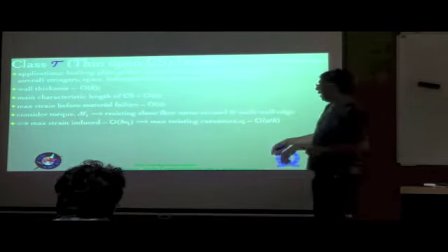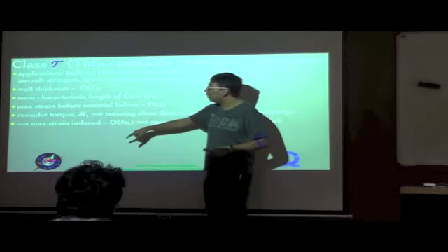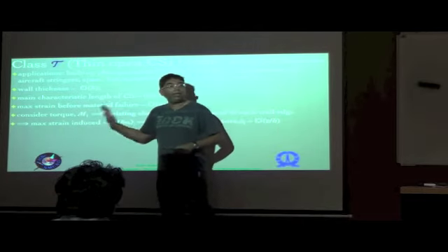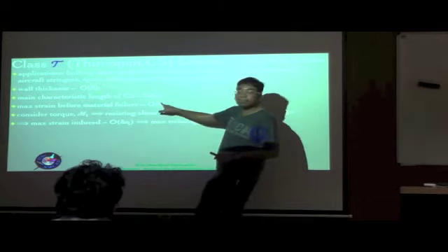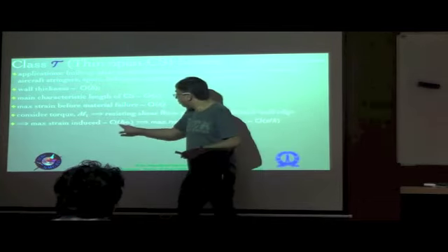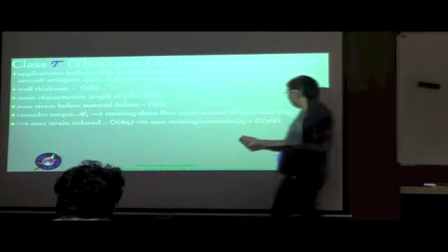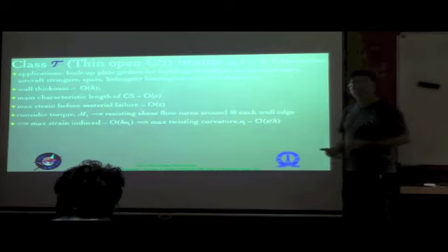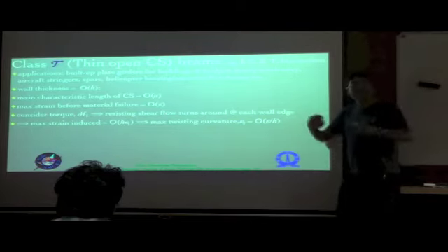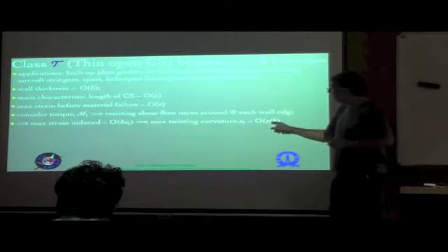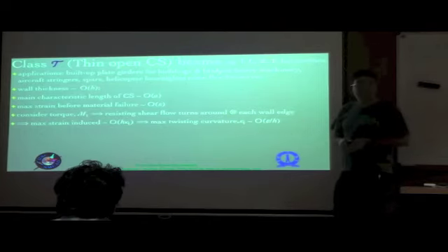So because of that fact, the order of magnitude of the maximum twisting curvature kappa 1 can be established because the maximum strain can go only up to the material failure, which is of the order of epsilon as we already discussed. So therefore, epsilon is of the order of h kappa 1. In other words, kappa 1 max can be at the most of the order of epsilon divided by h. Of course, it can be 0, but at the most, at the failure of the material, it can reach epsilon by h. So that is the order of magnitude of the twisting curvature.